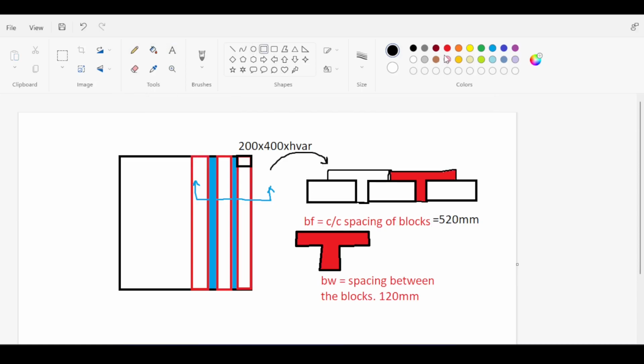What I'm talking about is the final rib on the edge, which doesn't count because usually the final rib doesn't exist. The final rib is replaced by a little beam, which is 20 millimeters of width and is being stirrupped. So usually we do not have a final rib in the last line. We have a beam that carries that. All right, with that being said, let's continue our work.